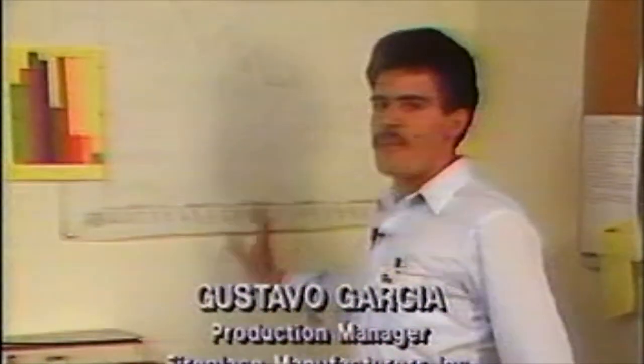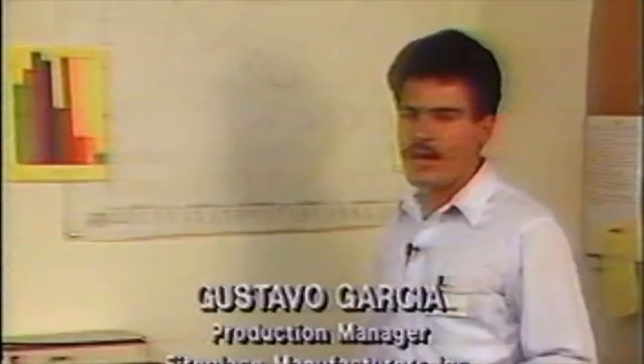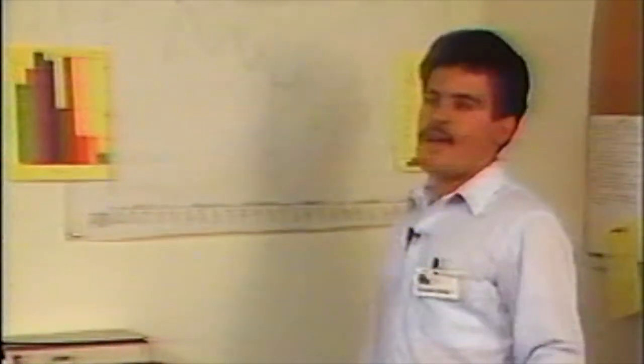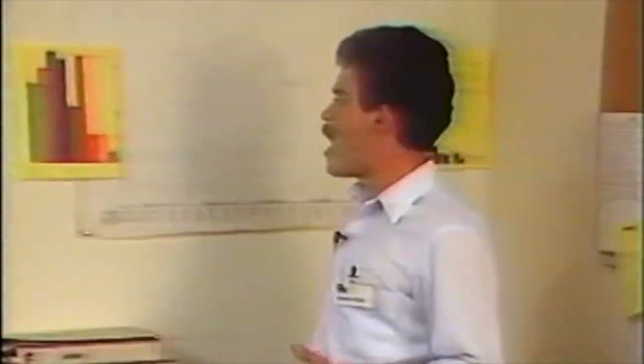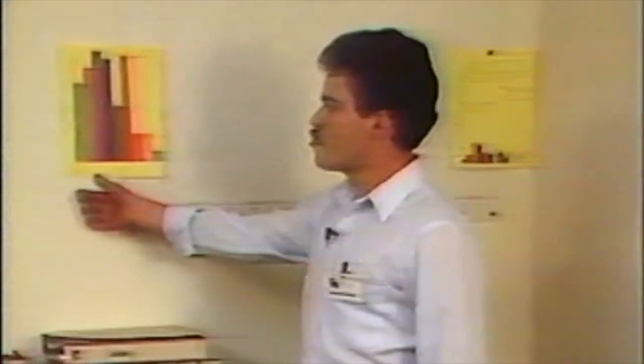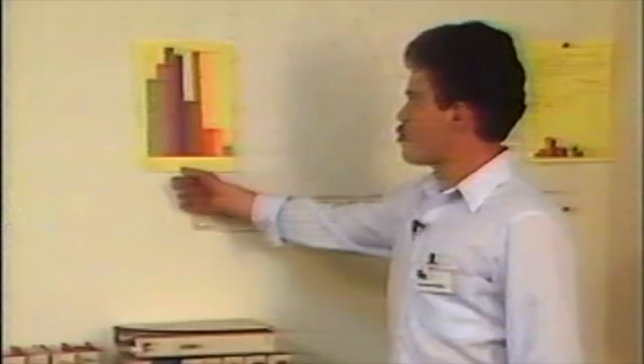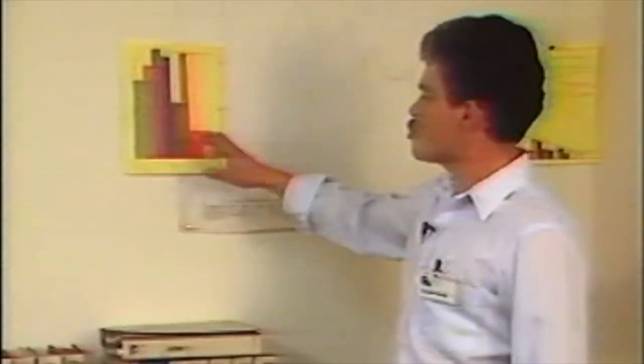As we have studied the line stop concept before, this example shows the use of problem-solving techniques to reduce the number of line stops. We started counting how many times the line stopped and from every station, and that will tell us how many problems we had. And right here we started doing this chart, and process control, it helps us to see how many times the line stopped, and right here tells us which stations, how many times every station did stop.